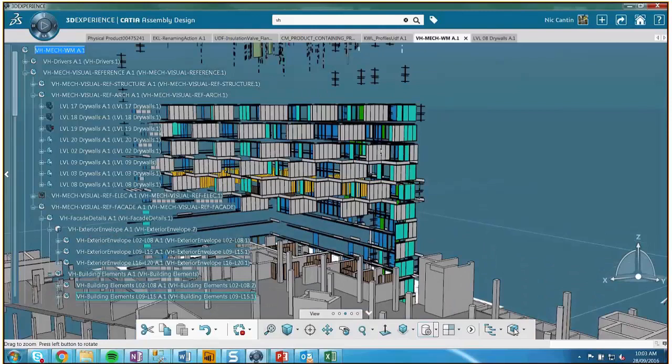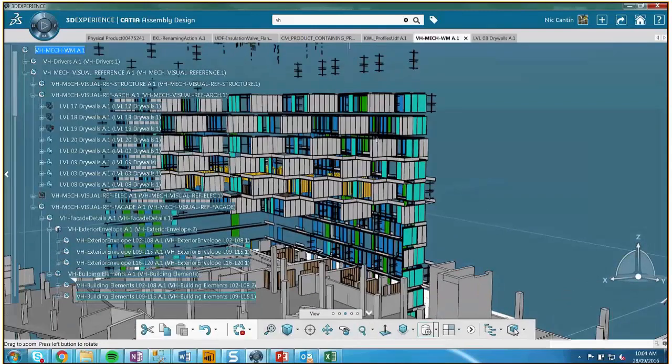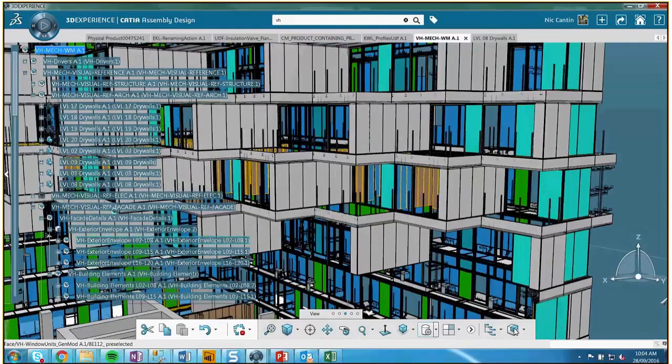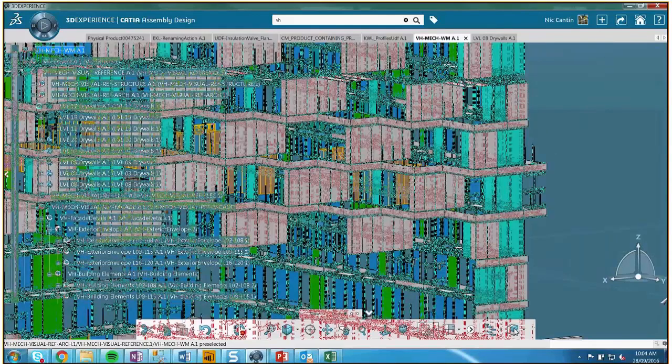But this is a really complicated facade assembly sequence, so we've broken it down into: we run a starter track, the top track, the actual panel, the cover panel, and then the soffit. So there's a 5-step scripting process to each panel, each floor. And then because it's got more of a twisting kind of geometry.